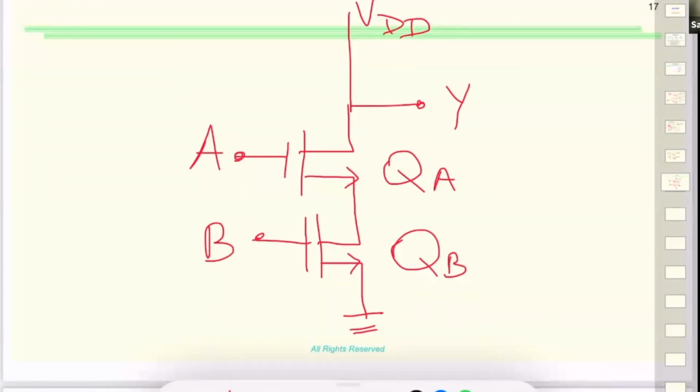So we call it pull down. It's just terminology, and there's a logical reasoning for why we call them what we call them. But from one transistor, we have to start thinking of a network instead of looking at each transistor. So we have the network of NMOS and PMOS, and we call NMOS pull down.